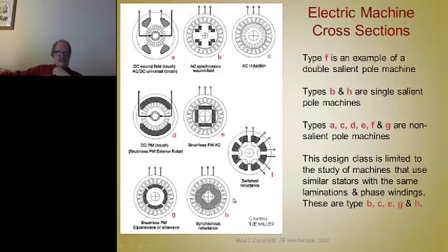And now here's an extreme example of a reluctance machine that has poles that look like a gear on the rotor and poles that look like a gear on the stator. If you look at this winding here, the flux is going to go through there like that. There's very little air gap in the circuit. It's all iron, with a very tiny clearance gap. But in this set of poles, there's lots of air gap in the circuit. You've got this great big air gap in there. So the inductance here is very low, and the inductance there is very high. There again, we're in quadrature here.